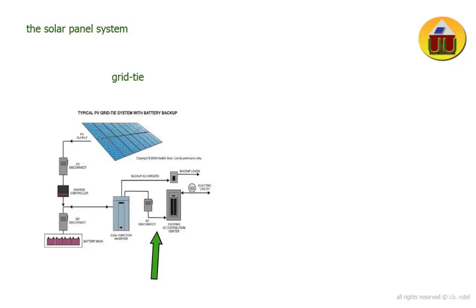In more recent systems, the panels can have the DC converted to AC right at the solar panel, which are called microinverters. And these can help to keep your solar power system providing maximum output. This type of system does not allow for power when the grid goes down. There is a safety system that prevents electricity from being produced and sent to the grid when the grid is not producing power, like in a power outage, so that linemen working on the electrical lines are not fatally surprised with electricity on a line when there shouldn't be.